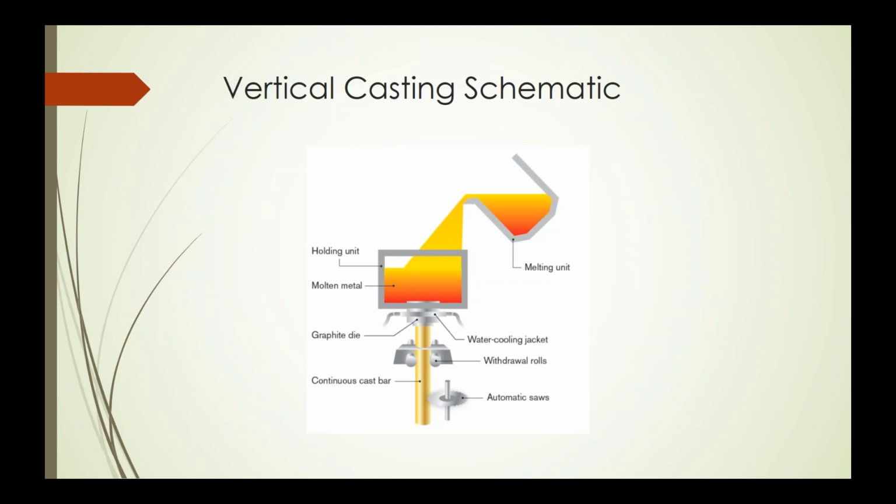You will see the beginning, maybe a glow in the middle, and then you'll see after it's solidified what final shape you're coming to, and maybe you're extracting it and using an automatic saw to cut it to length and remove the workpiece, which is then allowed to fully solidify or cool before it's finalized as far as processing.